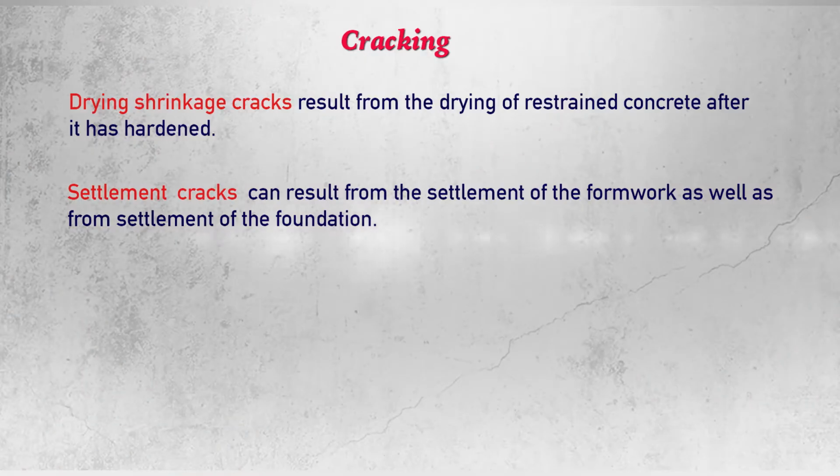Then there may be settlement cracks, and these settlement cracks may result from the settlement of the formwork as well as from settlement of the foundation. So if settlement of either the formwork or foundation occurs, it will cause cracks in the elements of the structure, and these cracks will be called settlement cracks.